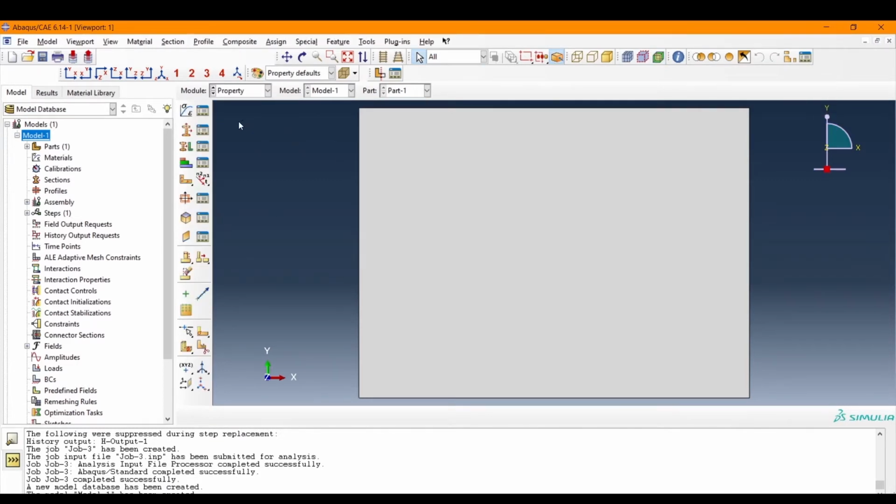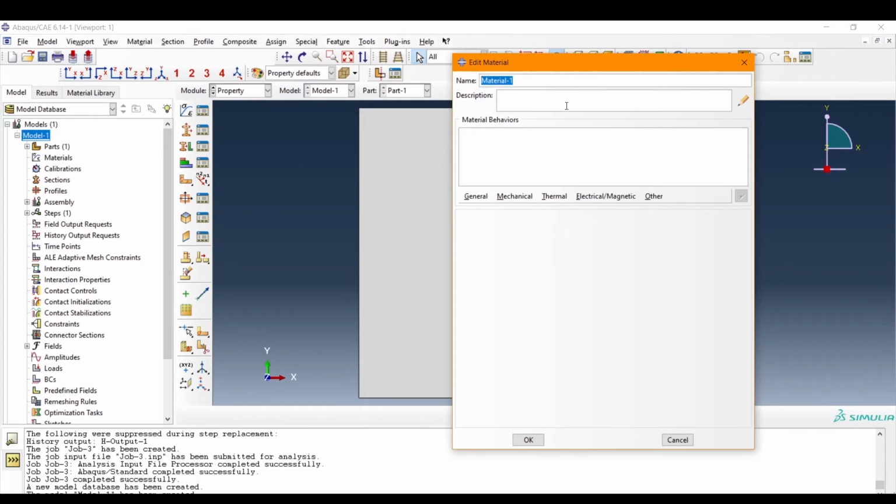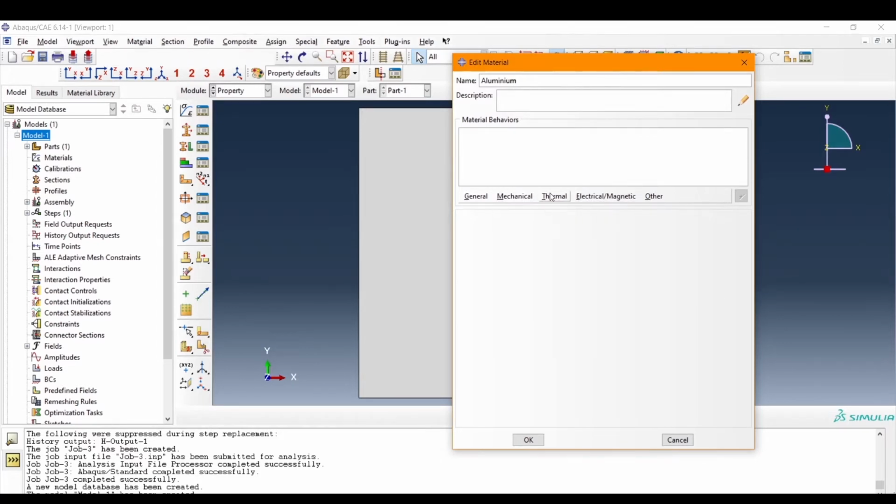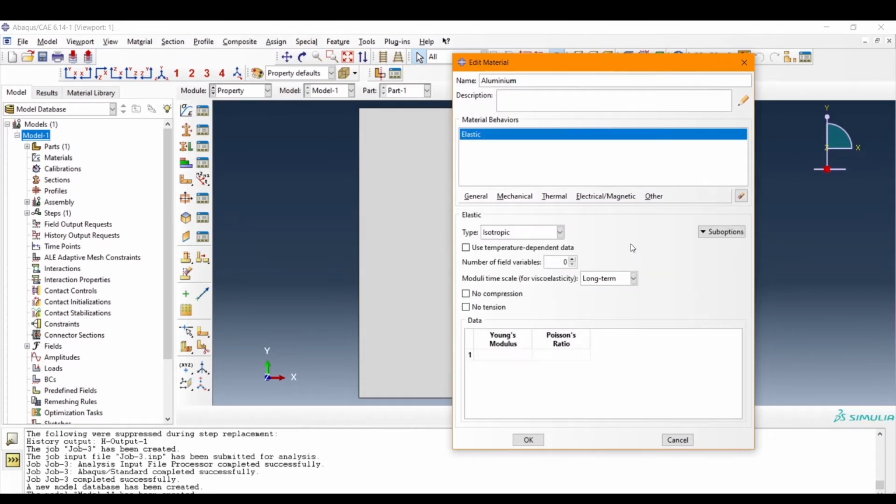Now we define the material. We will use aluminum. We only have to define the Young's modulus and the Poisson's ratio. Here we are using megapascals and millimeters. As you may already know, it's you who define the unit system in finite element softwares.